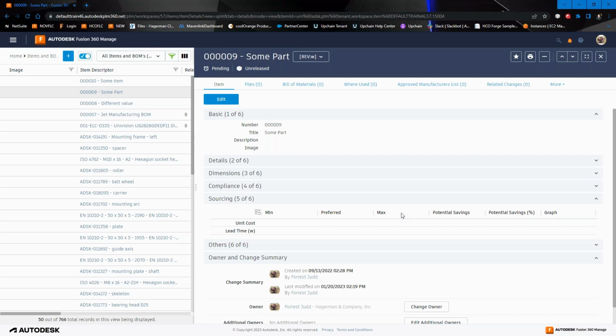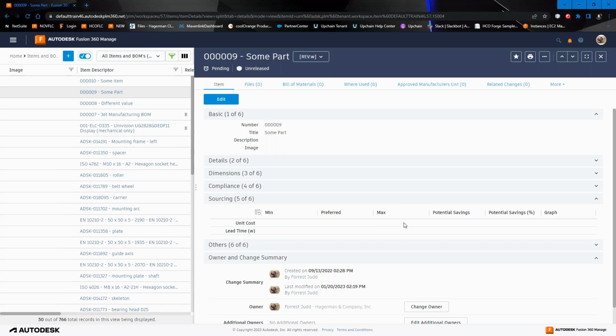You could absolutely, and I would argue, especially over the long term, should integrate your PLM with your ERP so that someone in procurement who mostly lives in ERP, they get a new quote on this thing you buy, they type in a number there, nobody retypes that number here. Either on demand or periodically, Fusion Manage either goes and pulls that information from ERP, or ERP sends it over and says there's an update to the cost on this part, update it.